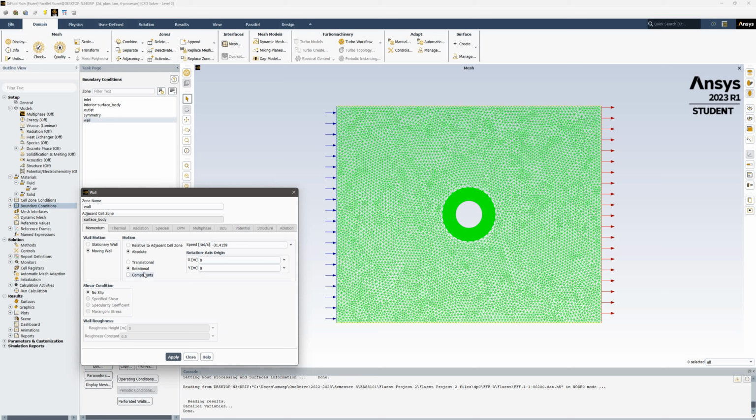Now that's the circulation speed, which is equal to 4 pi times the free stream velocity times the radius of the cylinder. So what this should give us is flow over the cylinder like this, and there should be a stagnation point at the very bottom of the cylinder. That's theoretically for inviscid flow, velocity potential flow. So that's where it's supposed to be.